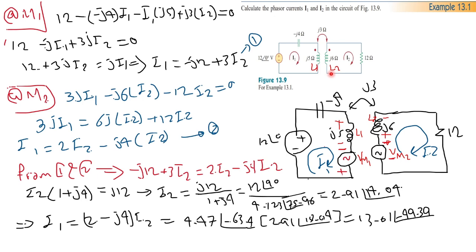When we analyze an AC circuit with mutual inductance, we can use a model. We can redraw the circuit after adding the mutually induced voltages. Here in the left circuit, we have a voltage drop around the capacitor and a voltage drop around the inductor L1. But due to the mutual inductance, there will be a mutually induced voltage around L1 due to L2.